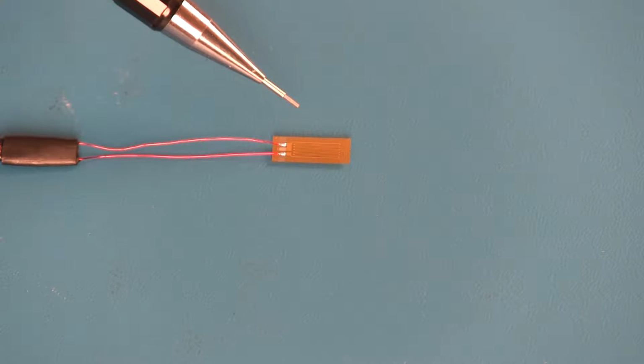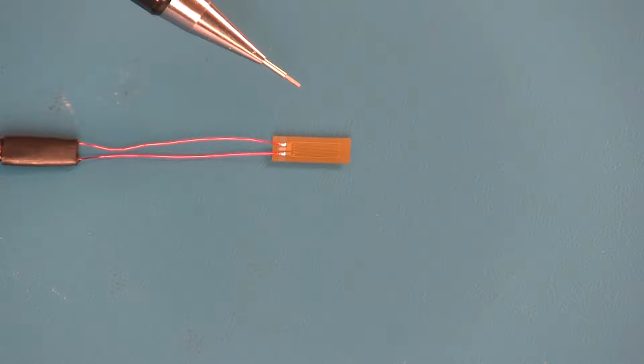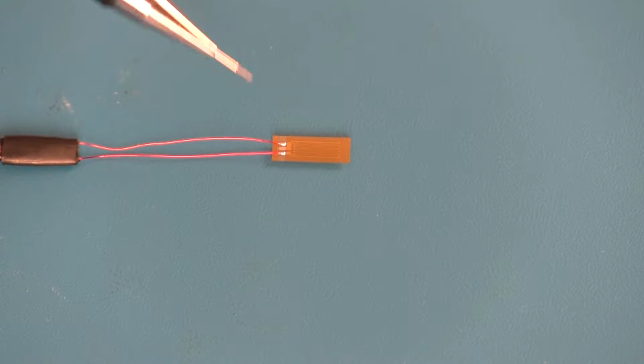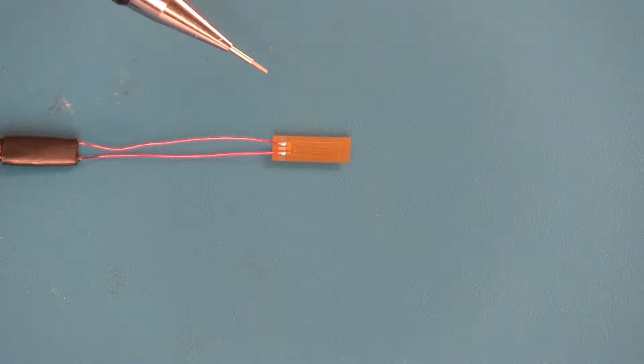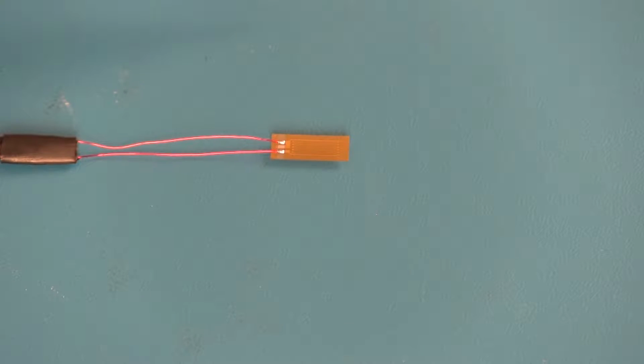This is a strain gauge. It consists of a thin wire or thin piece of metal foil which connects to these two terminals. When the strain gauge is stretched or bent, the wire or foil will stretch. Stretching or compressing the wire makes it either longer and thinner or shorter and thicker. This causes the electrical resistance of the wire to change, since long, thin wires have higher resistance than short, thick ones. Strain gauges are bonded to a piece of equipment to measure the amount of deflection the equipment is experiencing.